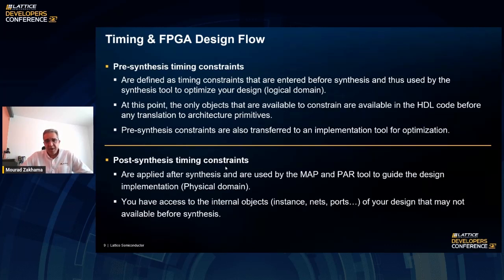Sometimes we are required to use post-synthesis constraints because some timing constraints that we need to apply are not visible in the pre-synthesis and are only visible after the synthesis. That's where we need to use post-synthesis timing constraints. In the post-synthesis timing constraint, you have access to the internal objects. These are instances, nets, and ports after the translation of your design after synthesis.